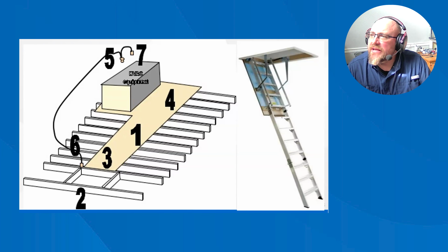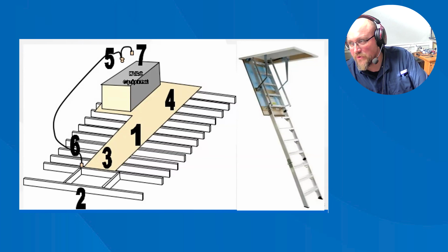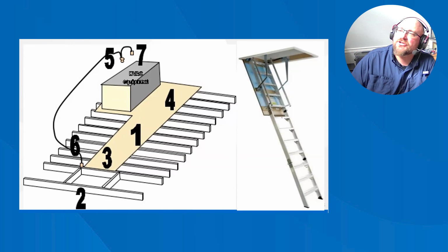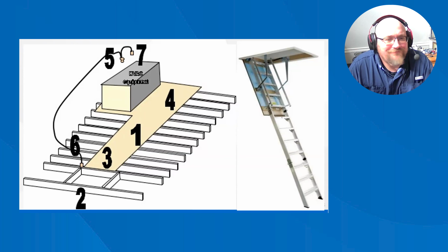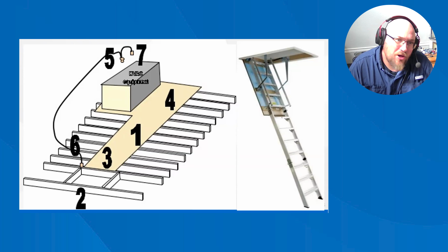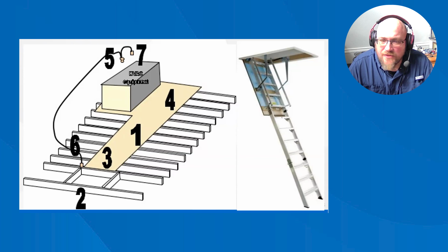Let's see. If there is a plumbing or electrical system or mechanical equipment in the attic space or in the underfloor crawl space, then the space should be accessible for inspection, service, and removal. Again, on older homes, you're going to find that this is not the case. A lot of times maybe equipment was smaller whenever they installed it, and now newer equipment is much larger and more difficult to get in. So just keep those things in mind.